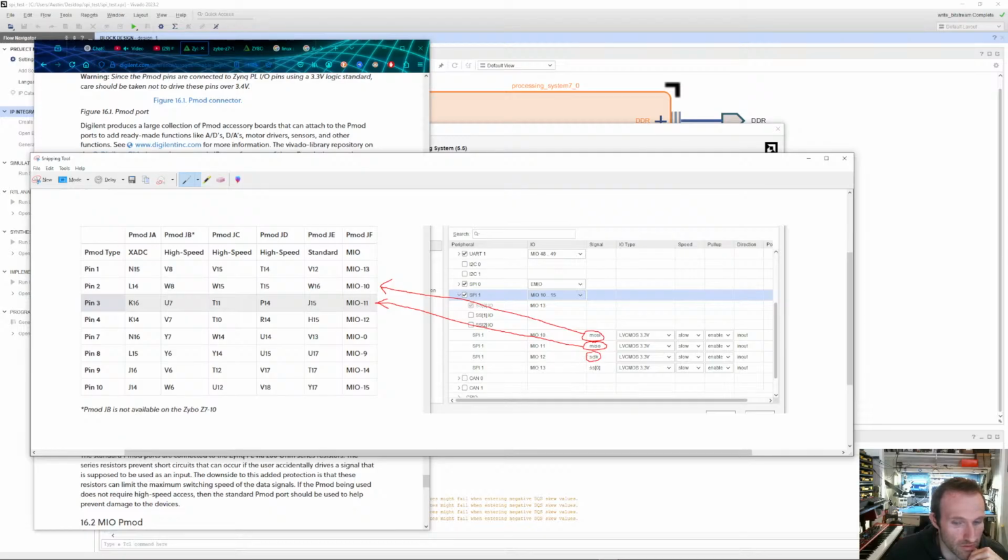I need to send, so I'm just looping MISO and MOSI back right now, but we need to send more out. You can kind of get away with not using these other signals for a loopback because you're just looping back to yourself. The system sending the data knows the clock rate, so you don't need to send that back because it's the master.